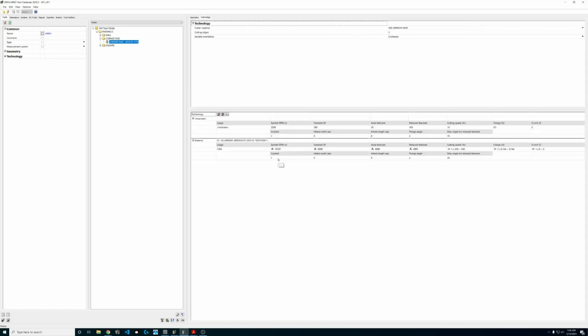You can do some other cool stuff with that function too, because guess what? Those numbers are just tied to M codes in the hyperMILL post. So you want to turn on the chip conveyor automatically? Great. Coolant 7 is chip conveyor. Now you just need to define coolant 7 as your chip conveyor M code.